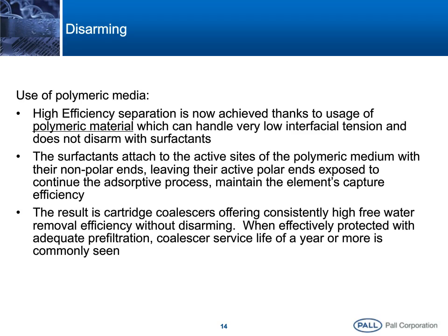They are able to work with the surfactants and orient so that if a surfactant attaches, it leaves the active polar end exposed to the main flow, and this provides the same capture function that is essential in continued coalescing efficiency. So these elements, when protected with adequate prefiltration to keep them clear of solids buildup, can last a year or more in continuous service.